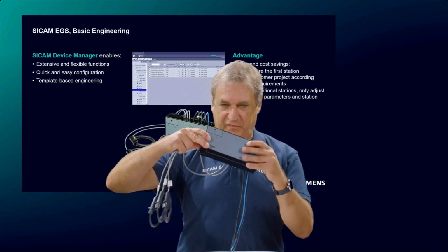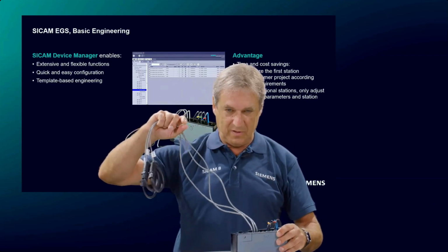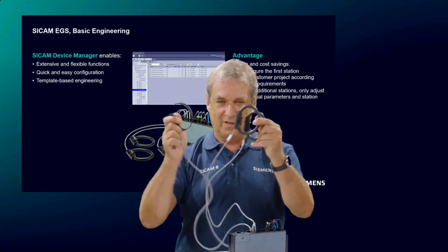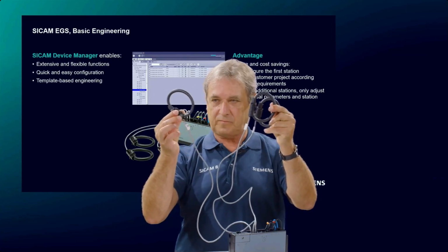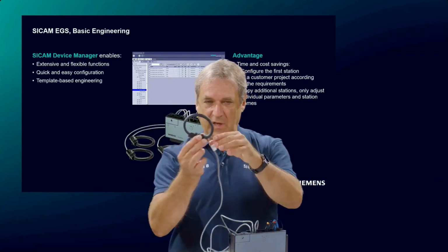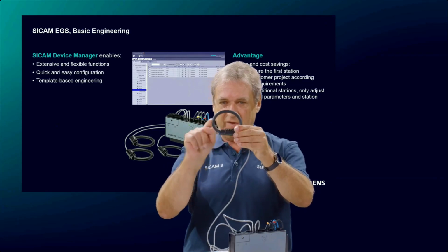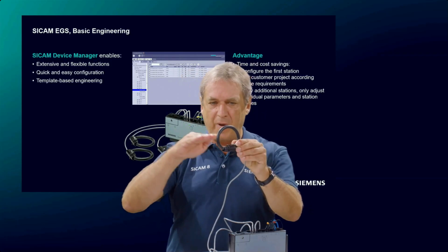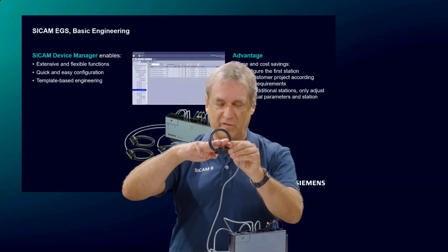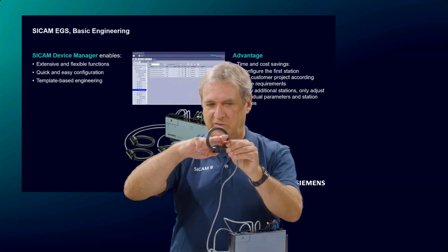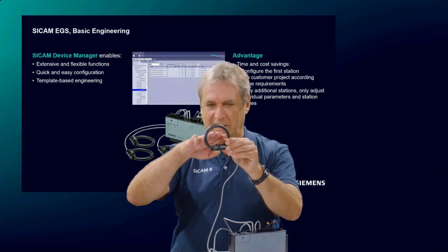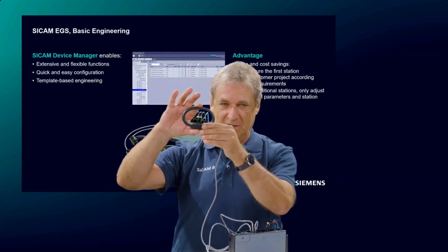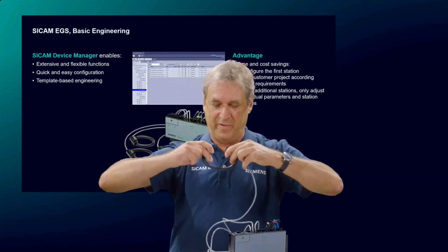We also explained it before. I put it now here on the table. Here you can see the 3 already attached Rogowski coils. Very important for you, you can see here the diameter is 7 centimeters. One of my customers has a copper bar coming from the low voltage transformer, and he told me that maybe 7 centimeters could be at the limit. As explained before, you can also slightly squeeze it. And of course, you can open it.